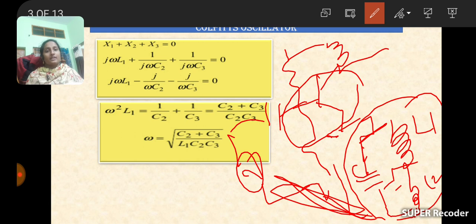If it depended on temperature, the leakage currents would increase, the temperature would increase automatically, and self-destruction may occur. For this reason we use the potential divider bias network. And here the transistor acts as an amplifier.